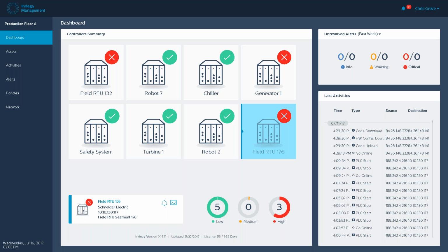Every successful known hack, whether it's Stuxnet, I know we all hate to hear that word, or Ukraine, was done that way. They went in locally and made a change to the control logic so that they could then make a change from someplace else. But you have to be able to get to that, and most people have secure firewalls and a lot of things to prevent attacks from the outside coming in. A lot of the successful threats are done from the inside.